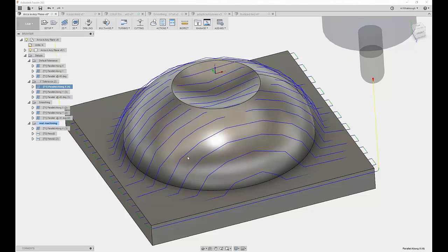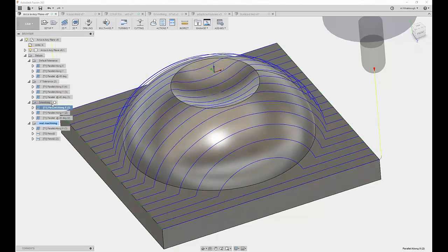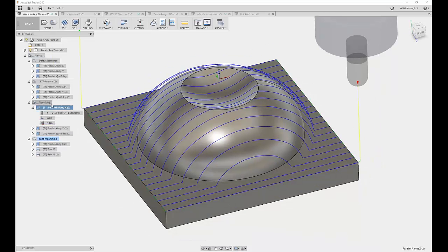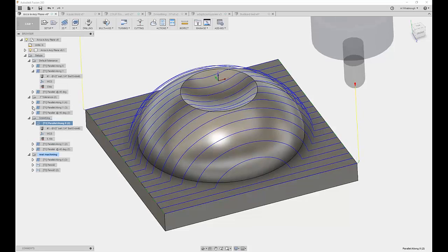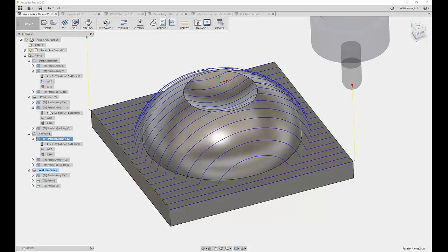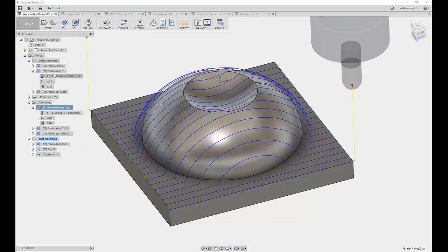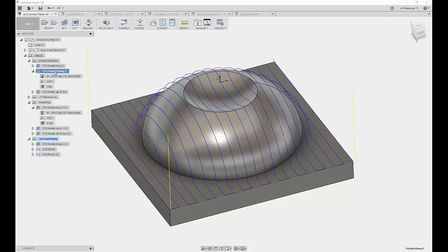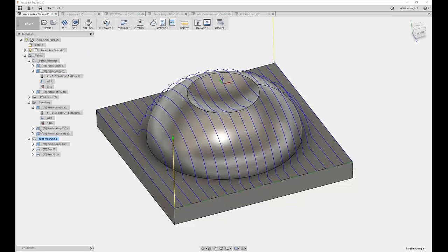Now the other thing that I thought was worth covering is I've often told people the trick that when you're using smoothing, you can look at the toolpath size, and that's going to give you a good idea of how things are going to run on your machine, but that's not completely accurate. So in the top case here, I've got my machining along Y where I didn't have smoothing enabled, and it's 33 KB. If I come down to the smoothing enabled, I've reduced my toolpath size to 5. So I've got a good idea that I made the toolpath a lot smaller with the smoothing.